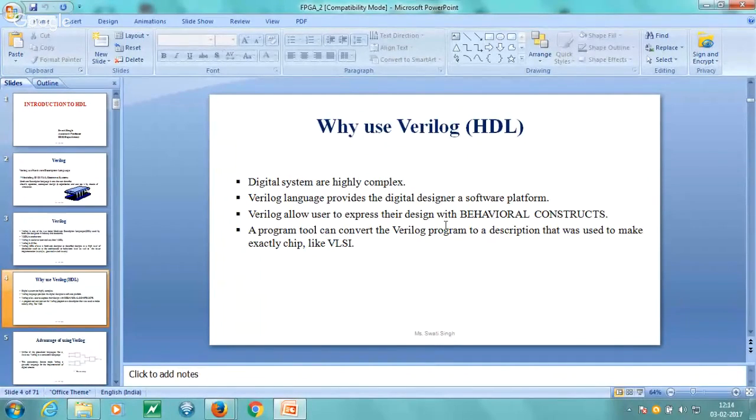So we can even design our own microcontroller on FPGA, and after checking the syntax, behavior simulation, and implementing it on your FPGA, you can give your design to a manufacturer company, and they will provide you your own logic IC.